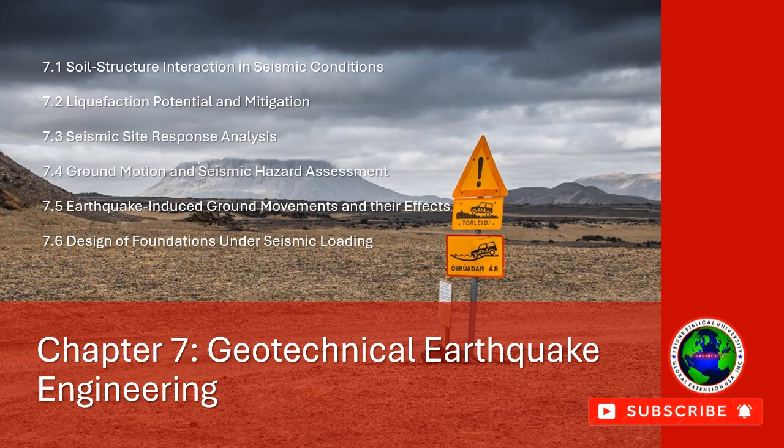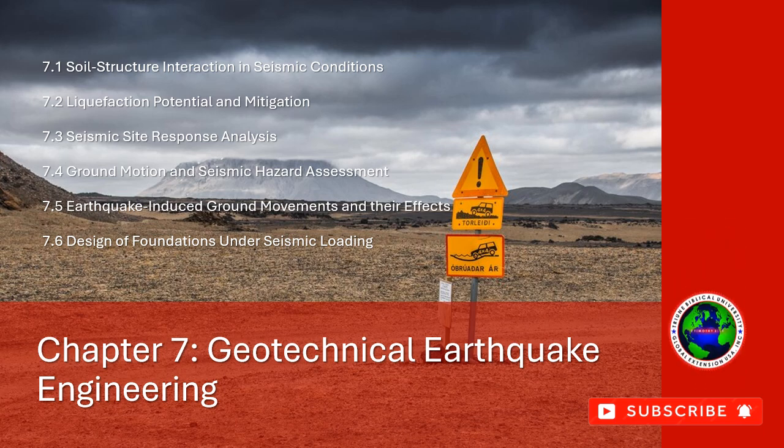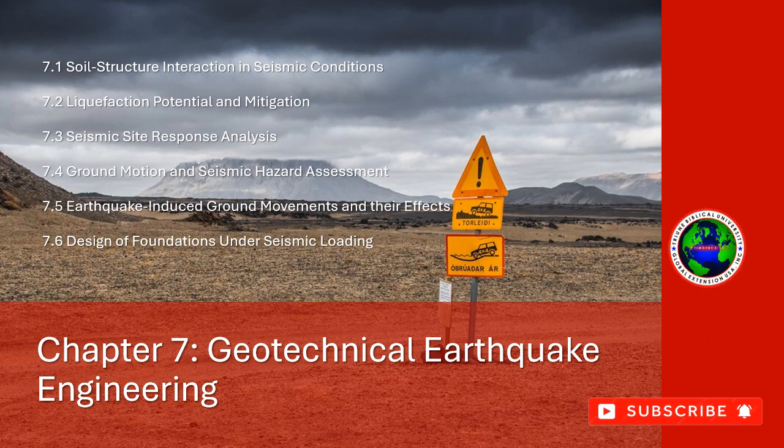1. Soil properties. Shear modulus and damping. The stiffness, shear modulus, and damping characteristics of the soil play a critical role in determining how the soil will deform under seismic loads. Strong, stiff soils transmit seismic waves more efficiently, while soft, loose soils may amplify ground motion and lead to greater displacement.